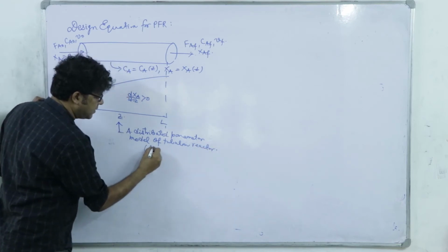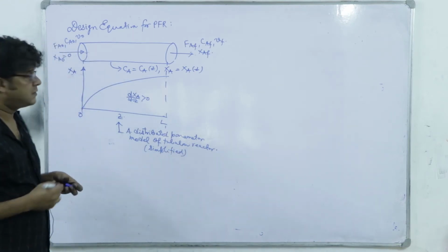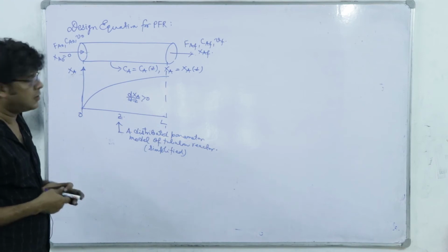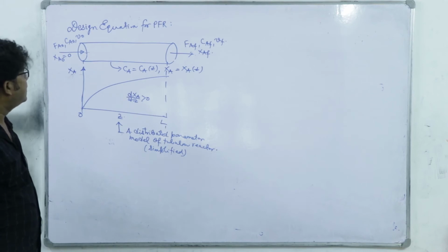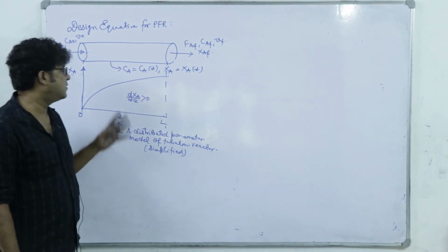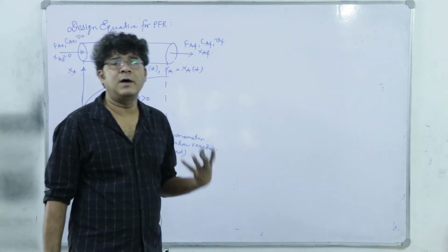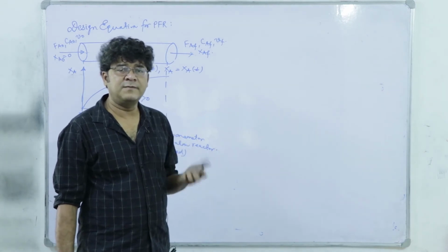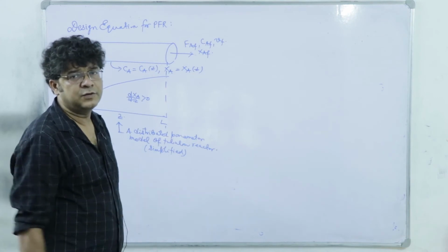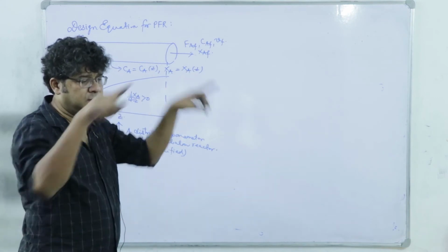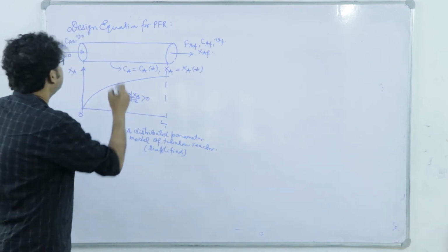It is definitely simplified, because in an actual reactor perfect radial mixing cannot be assumed. So the dimensionality of this problem increases from only CA(Z) to CA(R,Z). Anyway, whenever it is a distributed parameter model, we have to go by a differential control volume analysis, contrary to the previous CSTR, where we used an integral control volume incorporating the entire reactor.